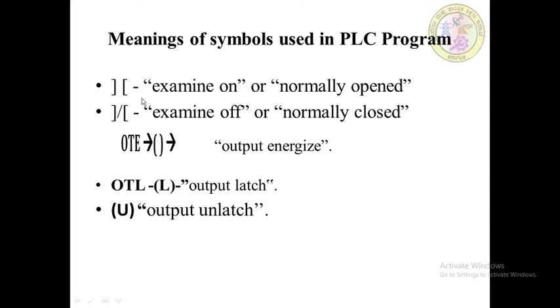This function is stored in a bit. If the corresponding memory bit is 1, then the respective rung will be continuously executed, and the corresponding output will be energized. A rung is one of the multiple horizontal program lines in a ladder logic. For example, if the corresponding bit is 0, then the rung will not be executed.